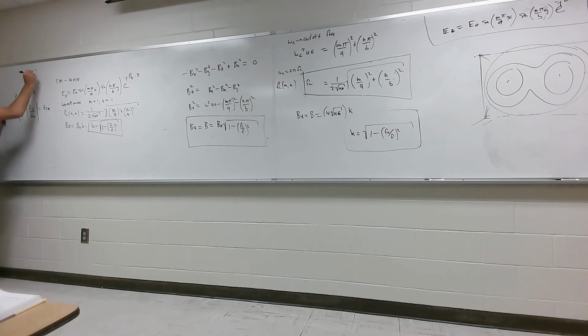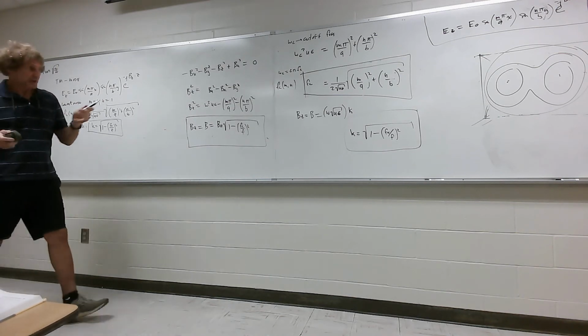This is 120 pi usually, if it's air-filled, but it would be that times the square root of mu relative over epsilon relative if it wasn't air-filled. Follow me, class? Can you all see it back there in the far back? All right. I'm just trying to summarize. This is what you need to know for TM. Now, something else, and I'll put it over here.